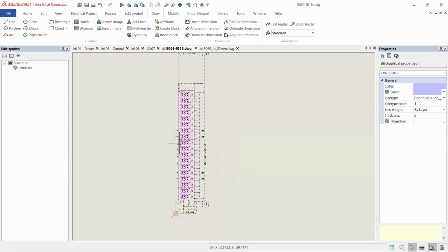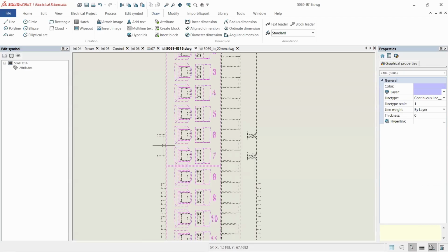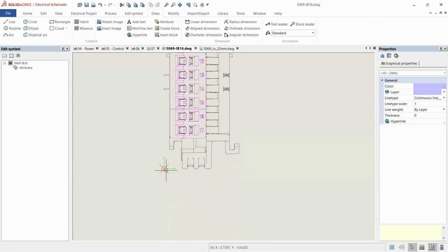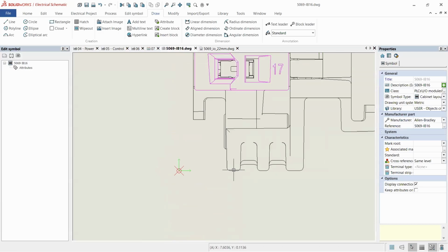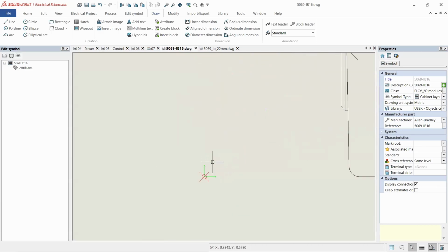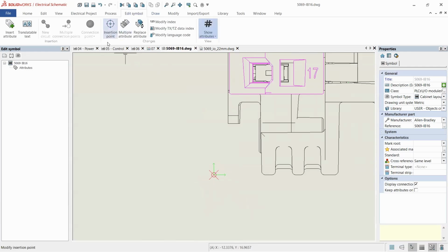So now that's kind of what we need to define in order to get this guy inserted into a drawing. Now, I like to insert these on purpose somewhere. The green is the origin, 0, 0. The red is not necessarily 0, 0. The red circle is where the symbol will be inserted, like where on our cursor the symbol will attach when we go to put it in a drawing. We can move that around under edit symbol and insertion point, right?